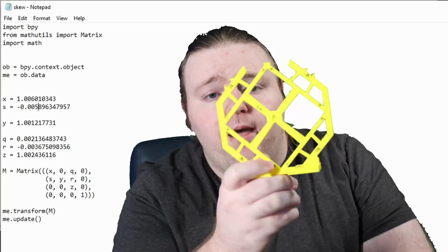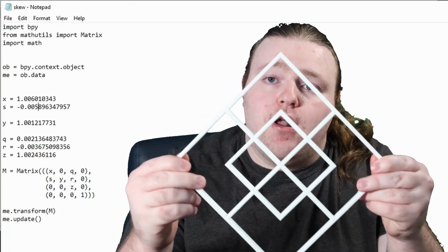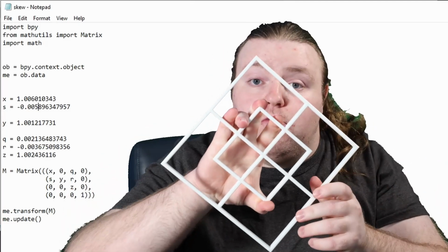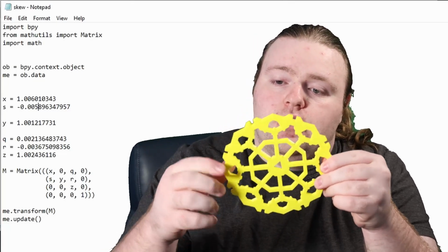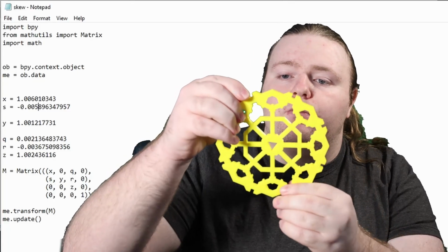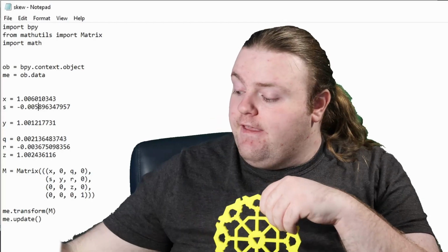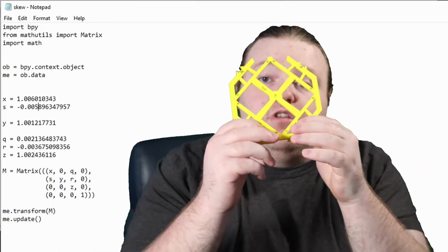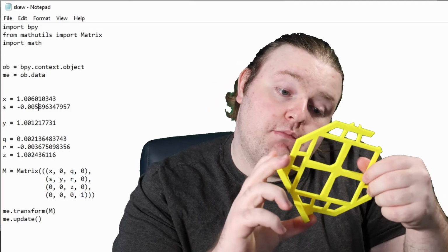And these do take some time, and I have problems with this. We're getting to the end of the video here, but the main problem is that these squares, like this print, are very flexible. So getting a reliable measurement is really bad. The benefit of this print is that in every direction, on the diagonals, which are the most important measurement, they are strongly supported. So there isn't a lot of give or stretch when you are measuring with the calipers. That is not true here. And so these have a little bit more flex than I would like, and I think that I can fix that, but right now it is not perfect.